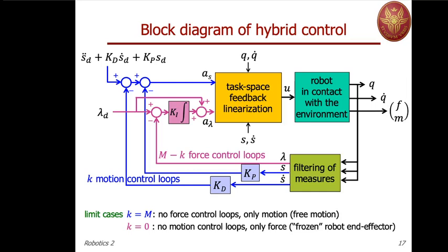But indeed, using the torques produced by the motors at the joints, we can regulate or assign any time profile to the contact forces and moments acting on the end effector, because this end effector is fully constrained by the environment. As I said, like if you're putting a solid block of concrete around the end effector, and indeed the robot will not move.